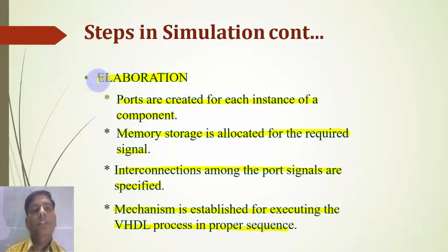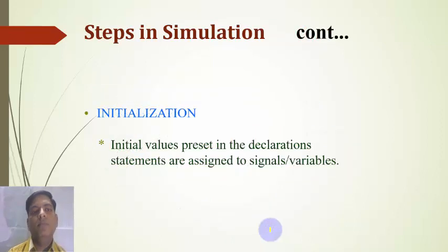Second, elaboration means ports are created for each instance of a component. Memory storage is allocated for the required signals. Then interconnections among the port signals are specified. Then a mechanism is established for executing the VHDL processes in proper sequence.